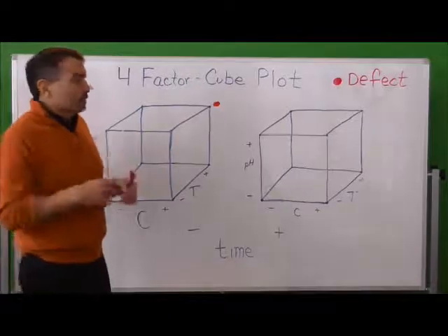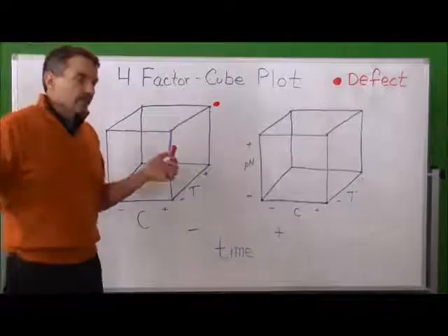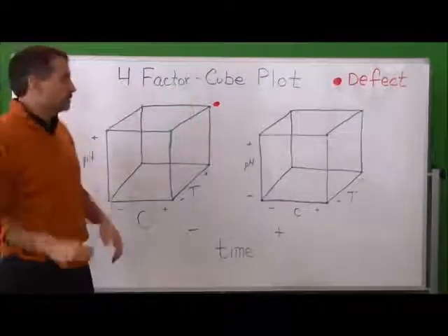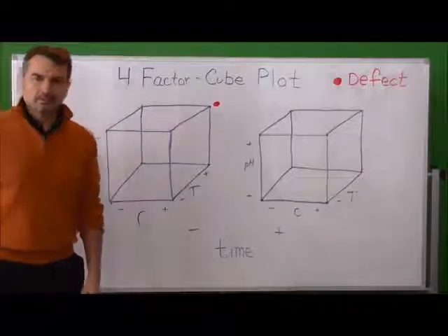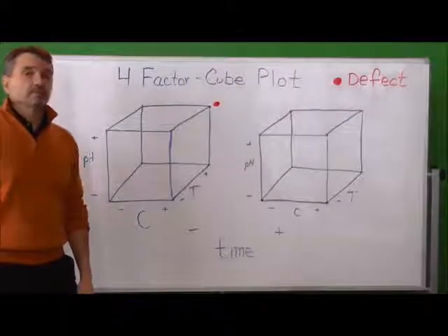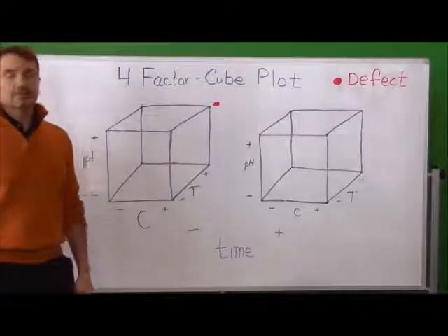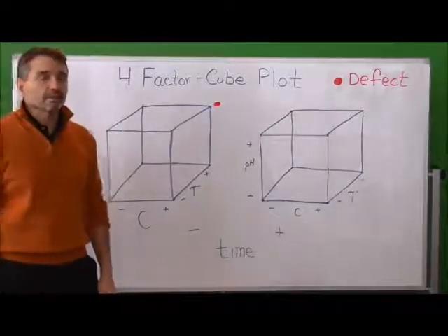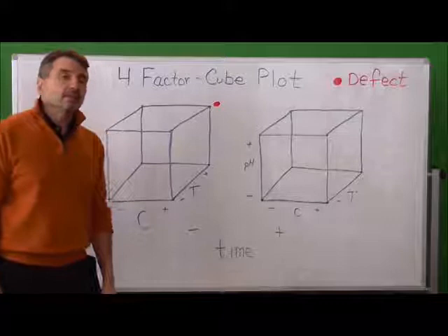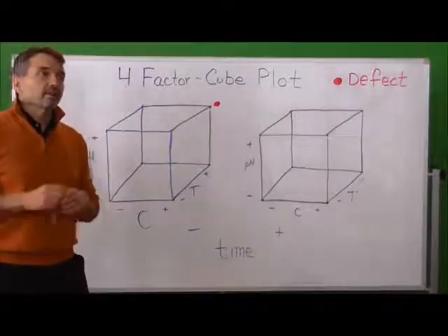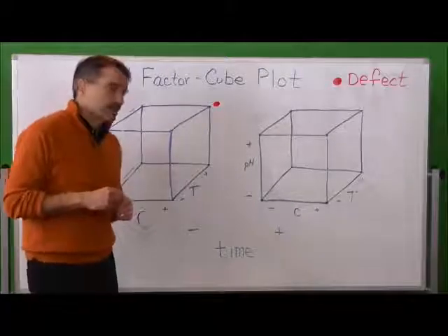Okay, so what do we have covered here? Well, we went through the whole development of the process. We went through the development of the entire four-way development of it, the 16 runs. The Q plots will tell you which direction to go in. The mathematics will tell you as well, but very quickly and very easily, the Q plots will tell you what direction to go in. And when you're doing these out on the factory floor, or in certain other processes that are non-factory related, this is a very quick area to get quick results and to understand the process and to understand where to go next.